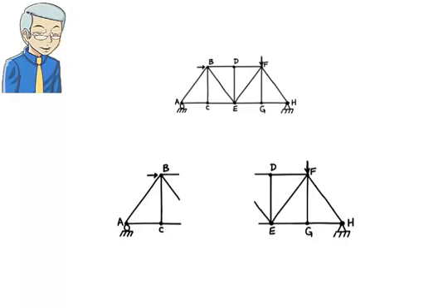This method of cutting a structure into parts is a convenient way for determining some of the unknown member forces without needing to analyze the entire truss. More specifically, the method enables us to rather quickly calculate the force in one or more cut truss members. In this particular example, we can determine the force in members BD, BE and CE without needing to analyze the entire structure. Generally, we may be able to cut a truss in several ways.